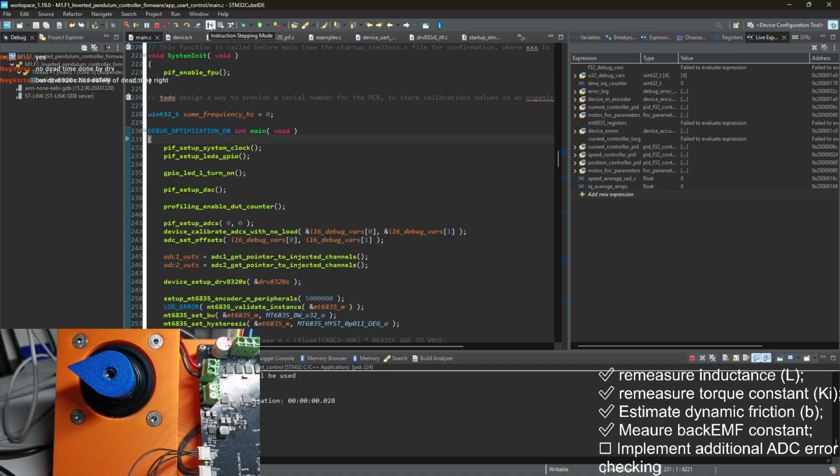So if you can use a hardware driver, just use it. And if you plan to use a hardware driver, why do you need 6 PWMs? Because 6 PWMs in this case don't make much sense. You might as well use 3, because why do you need 6, if your dead times are provided by hardware? The only reason to use 6 is to provide the times yourself, I believe. Maybe I'm wrong, but I hope I'm not.